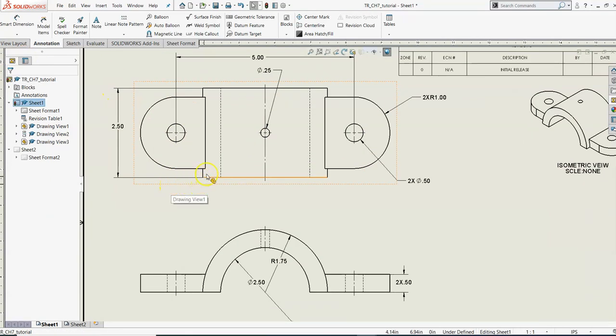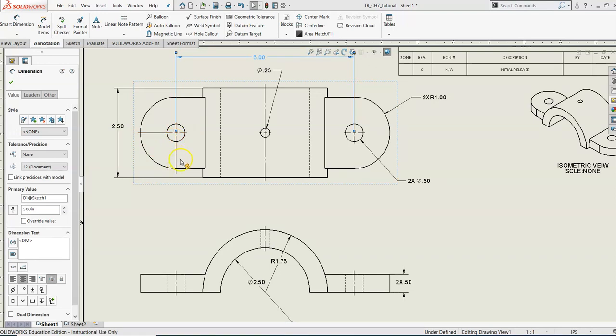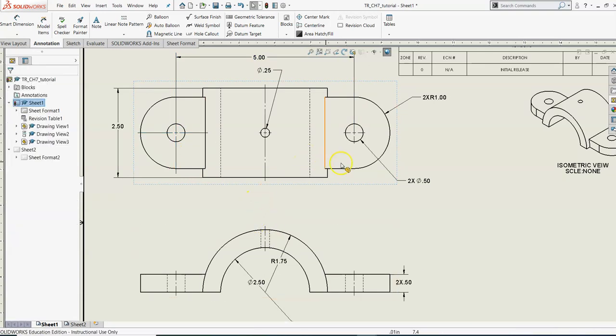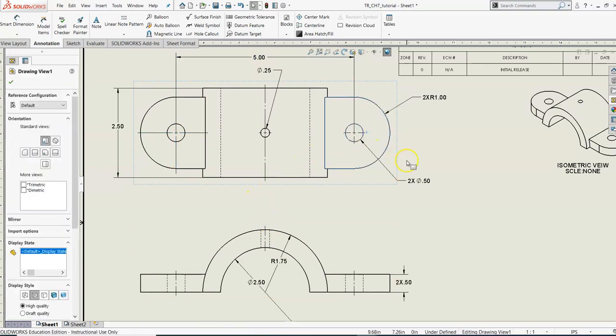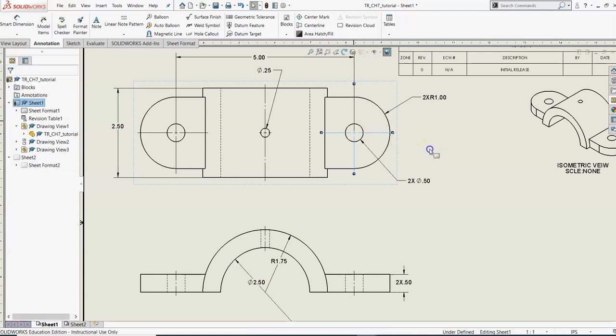All right. So another thing ASME standards want, if this hole is centered with this, we should be extending this. Okay. We want to extend these lines. Okay, that's proper ASME standards. Okay, we'll be doing that here. Okay. If you look, it comes out a little funky.